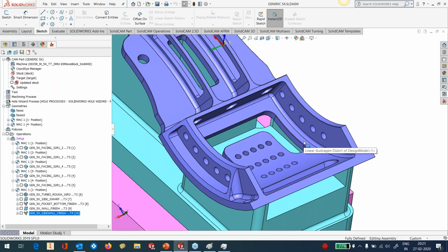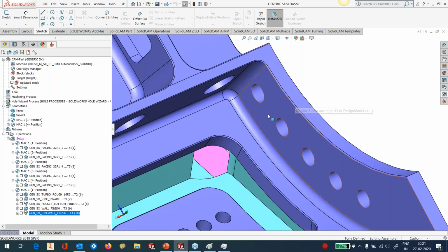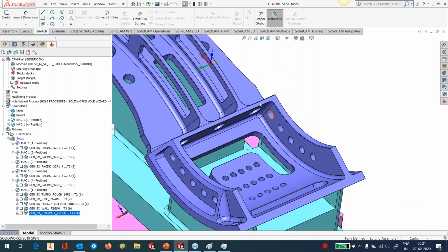Right. Now let's come to the main area that we need to be careful about. Although some of our technologies today can handle holes and other things as part of the links, a better way is always to close them when you're doing 5-axis, especially when you're using the circle end mills or our barrel tools. Okay, because now I'm going to use barrel tools to machine the inside of this region, the walls. I'm going to use barrel tools.